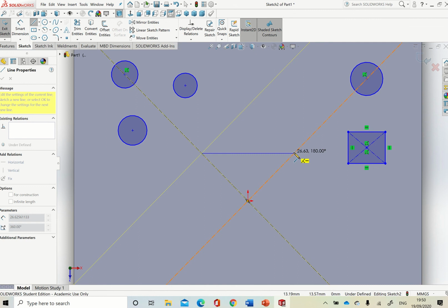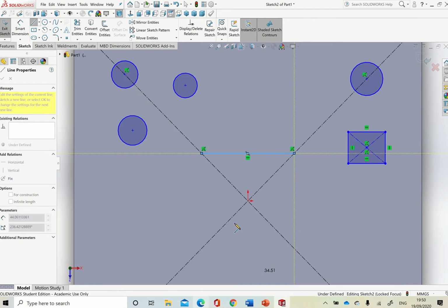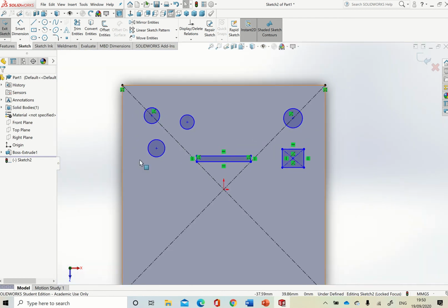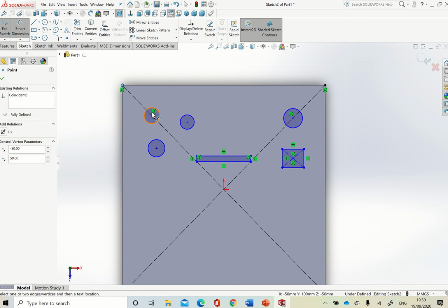So the highlighted is telling me that my line is straight. So I can see there it's 180. If I get it back, yeah, 180, and then it's coincident with that axis. I might just go back into the PDF just to make sure. Yep, correct. So it doesn't matter about the dimensions. We're going to make our dimensions now. So I'm happy with that. So these are all the components we're going to have in the desk tidy. So the next step is dimensioning.